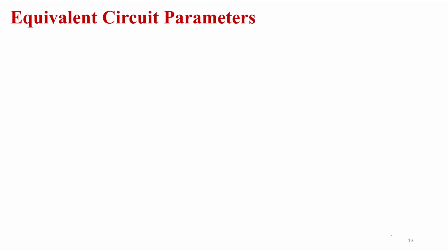Equivalent circuit parameters, which you have already done in your lab, right? What are the tests you have done in your lab for finding this equivalent circuit? OCC, what is OCC? Yes, no load test, then Blocked-Rotor test, and what else? To find out resistance, we do a resistance test, right?